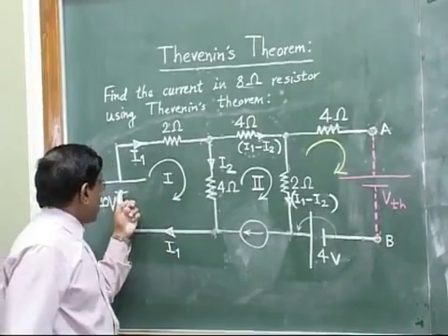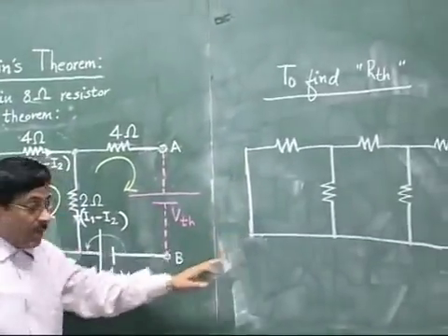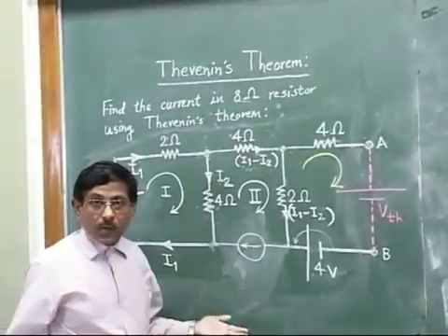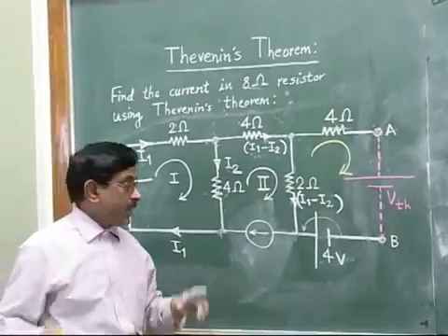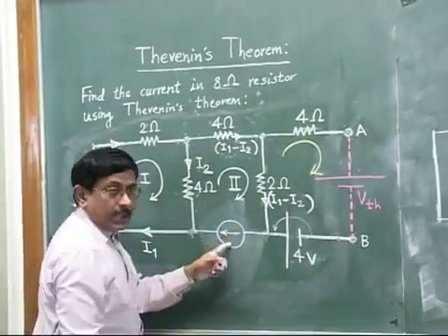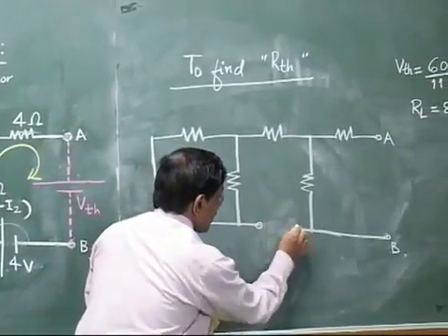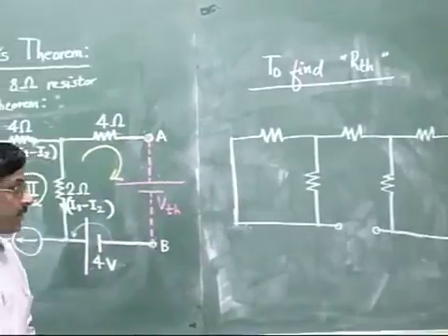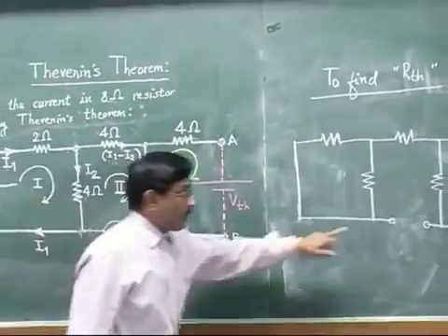Now, as we have shorted the voltage source, for a current source we have to open circuit it. So the simple rule: a voltage source is short circuited, and a current source is open circuited. In that circuit this source would be open, meaning it would be this situation.